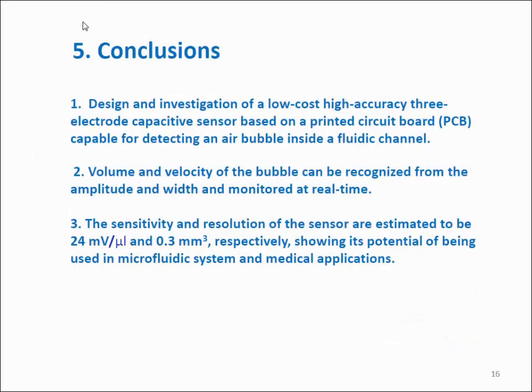So this is my conclusion. We have designed and investigated low cost and highly accurate capacitive sensors based on the printed circuit board, and it's able to detect an air bubble inside of fluidic channels, and also the volume and the speed of the air bubble can be recognized from the amplitude and width of the output signals.